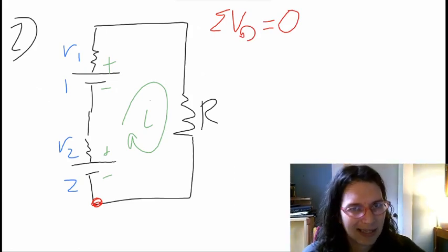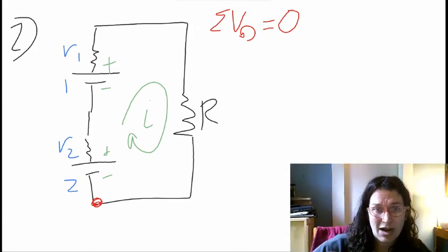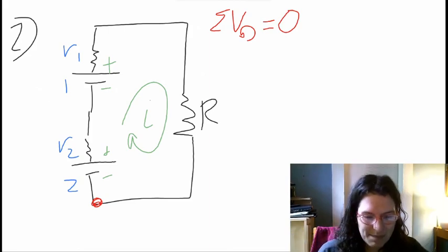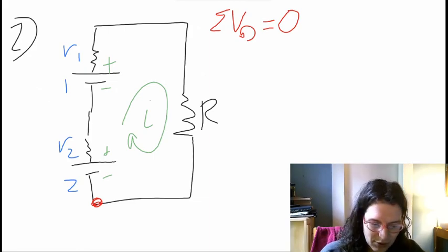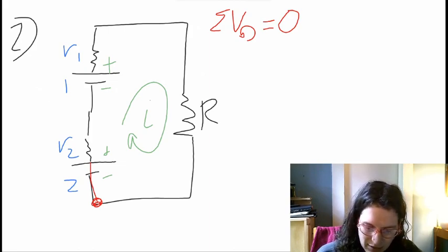Shouldn't everything be adding a voltage? Well, keep in mind, to go back to that last problem, we drop voltage over a resistor. In other words, a resistor uses up voltage, whereas a battery is going to add voltage to a circuit. So let's go ahead and take a look at how this would work. We'll start at this point and we'll go up. As we move up, we go over our first battery, and our first battery is going to have our electromotive force, and we called it battery 2.